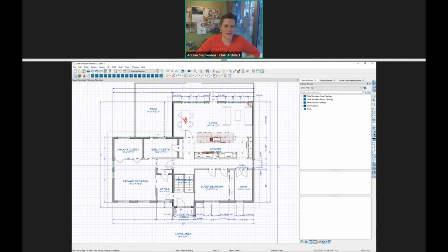I think there's kind of two factors at play here. For whatever reason, for that room label, the center node essentially is not aligned exactly on that center point. The other factor is if you have a room that is non-square, the program has a really tough time figuring out what the center actually is.